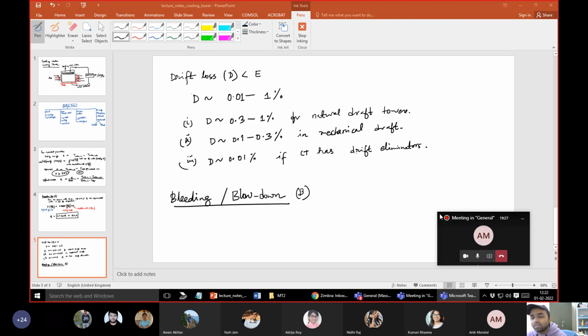And what are these dissolved solids? I mean, all of you know very well, these dissolved solids are nothing but chlorides, carbonates, sulfates that are present in water, right? So these solids essentially start to form scale over the surface of these equipments, as a result, an additional layer on the surface. And that layer will have different heat transfer properties. Its thermal conductivity would be low, and the heat transfer would be significantly reduced from its designed performance, isn't it? That is the problem with scaling.